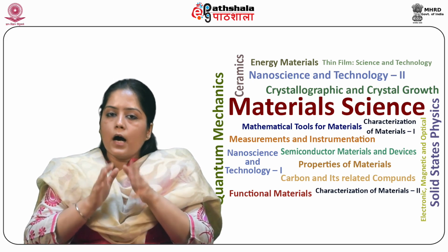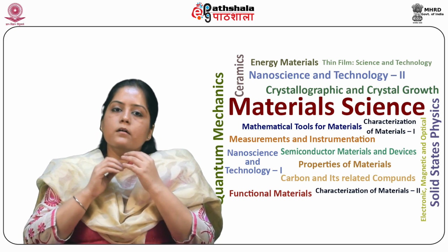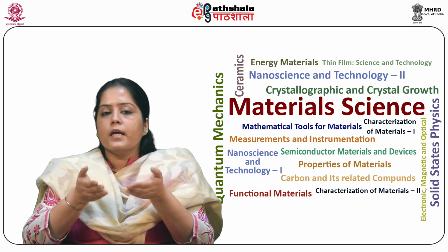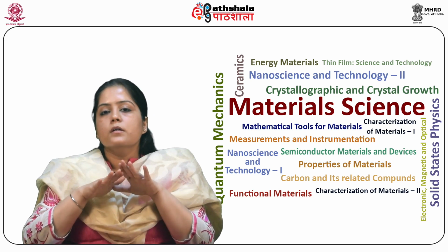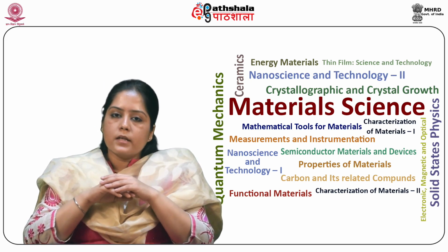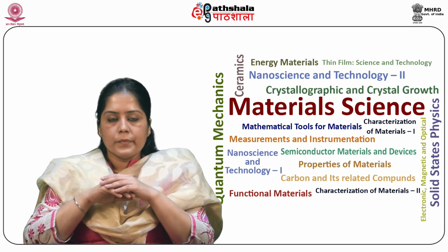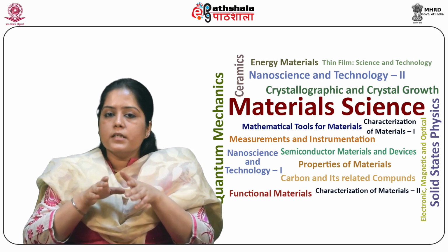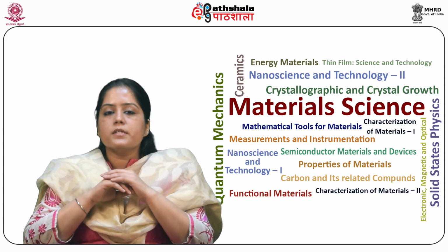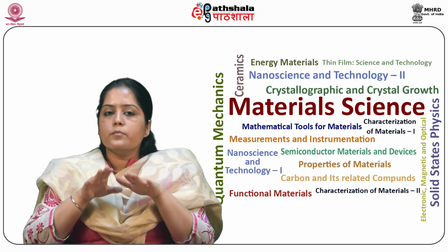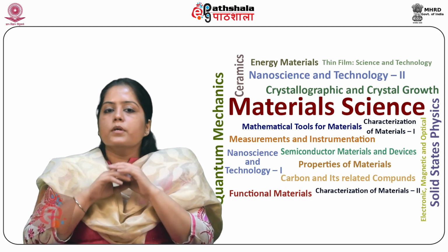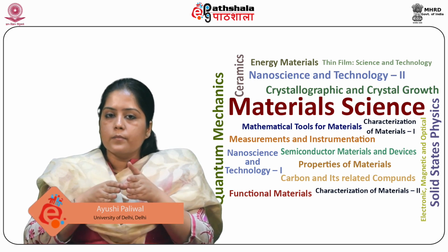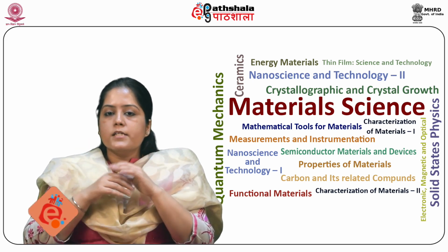However, the high cost of the material is a major hurdle. Copper sulfide, cadmium sulfide cells can be easily fabricated on small grained polycrystalline cadmium sulfide. It is potentially a low cost technology. The difficulty of achieving 10% efficiency on a production basis, combined with stringent encapsulation to prevent degradation, may prevent its widespread use.